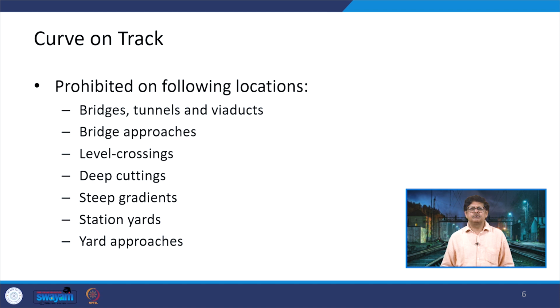Now, let us talk about the locations where the curves shall not be provided. If they are required, they should be used before or after those locations. So, what are those prohibited locations? The very first one: bridges, tunnels or viaducts.